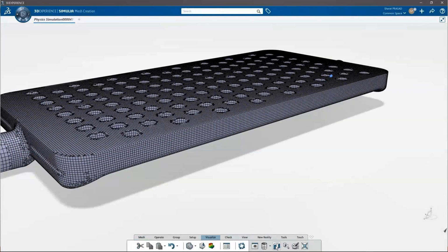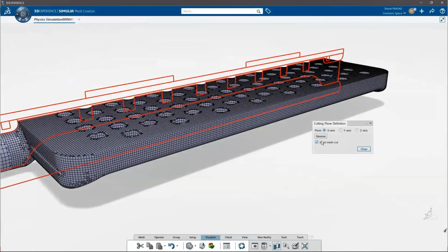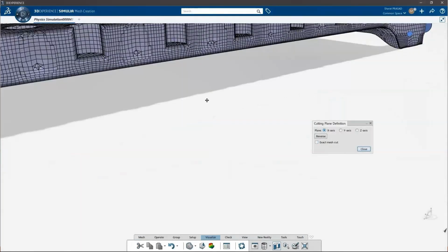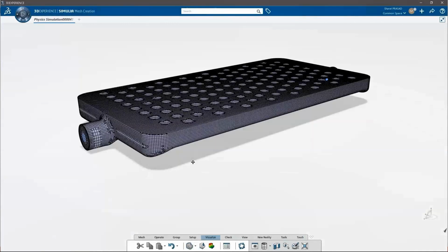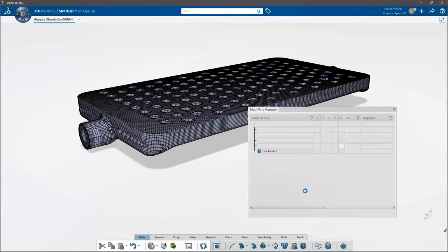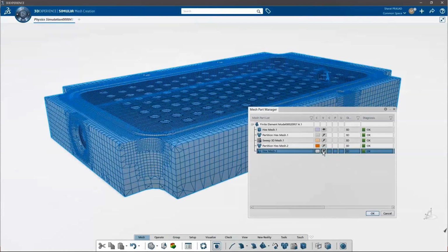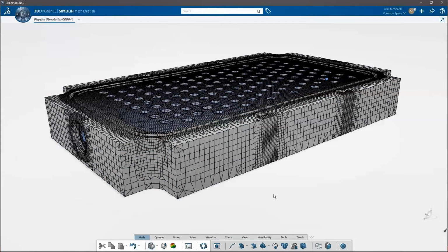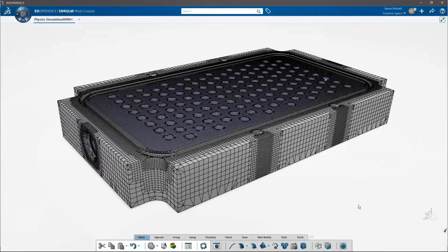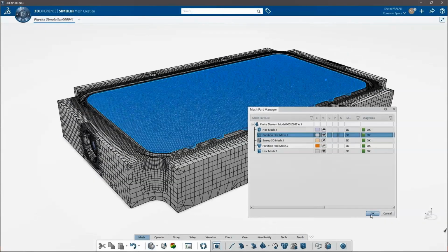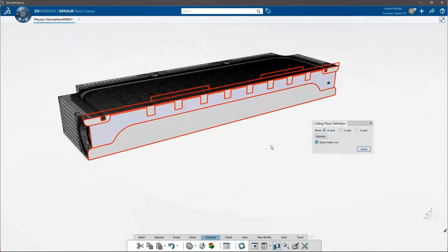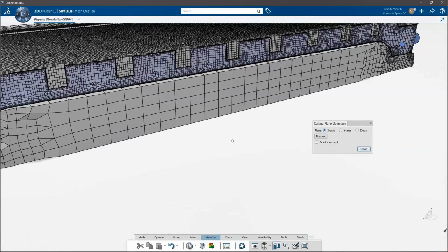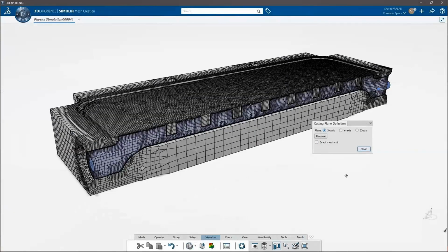So this is the mesh that has been created. It's a gradient mesh, of course, as you can see, and it's always hex dominated, like I have been saying. And that's the bounding box under which the study will be carried out. Even for creating the bounding box, we do have the automatic option wherein I can input the dimensions in X, Y, and Z, and the tool is going to automatically create the bounding box, and later on it's also going to mesh it as required.